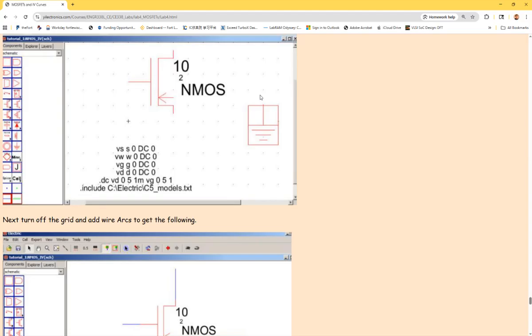You just place this little ground symbol in the schematic, and that's it. And you are not connecting this to anywhere because you don't have the body connection for that version. All the VDD symbols and the ground symbols serve as global symbols, and can go up and down in between different layers. I don't know if you understand what I'm saying here.